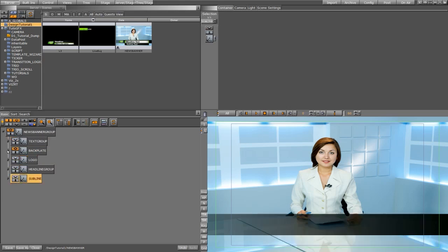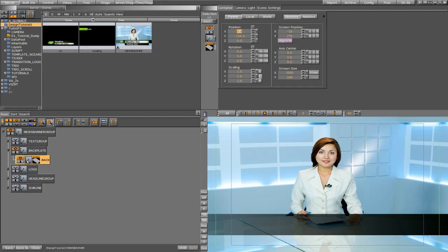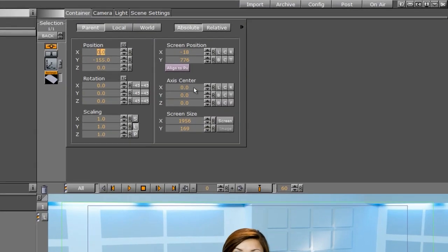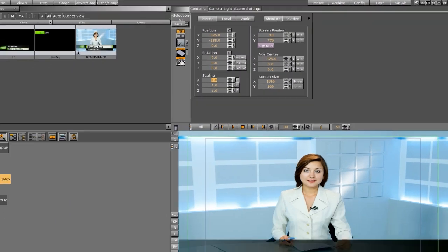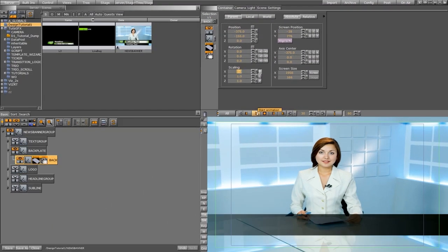animating these on. I'm going to start with this back plate. So I'm going to come into this rectangle. I'm going to go into the transformation editor. I'm going to set my axis center to left again. I'm going to set my scaling to single. I'm going to advance my timeline out to where I want it to land, roughly about 30. I'm going to set a keyframe. I'm then going to rewind my timeline to 0 and set my scaling to 0, then set keyframe again. Here I get the little animation. If I hit play, you can see how that scales on.